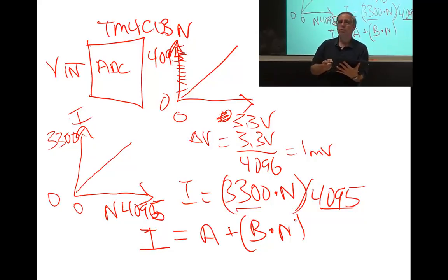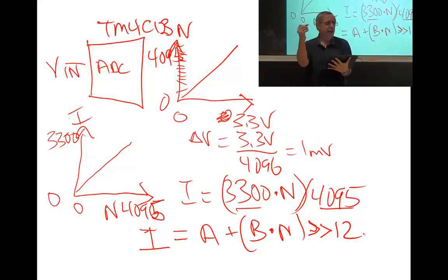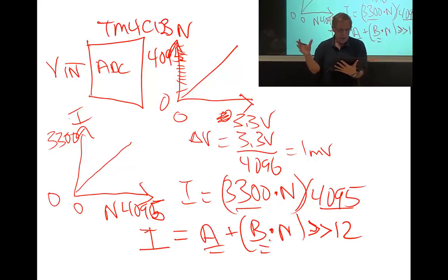Because it's a calculation, what type of math should I use to represent this binary fixed point? I'm going to pick a power of 2 which is big enough. Maybe I should have chosen 16 or 32 or whatever. It's a 12-bit D to A converter, so 12 bits is probably enough. And so I'm going to find constants A and B, which I'll program into my system. I'll calculate n. And I'll use binary fixed point to represent the number.